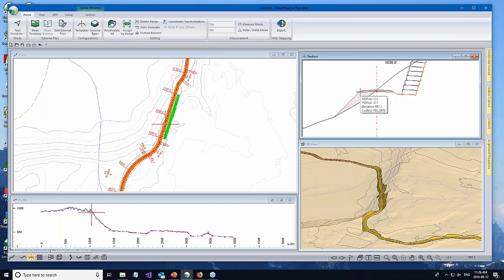If you just hover over points in the cross section, you'll see there's a code there. Typically the ditch is called DIR for the inside right, and DOR for the outside right, and similarly DIL and DOL. So I can choose to shade between any two pairs of codes.